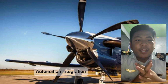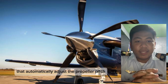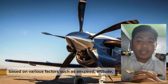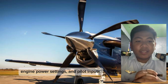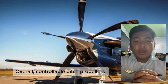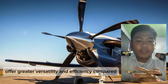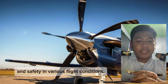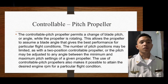Automation integration. Modern aircraft often feature electronic control systems that automatically adjust the propeller pitch based on various factors such as airspeed, altitude, engine power settings, and pilot inputs. Overall, controllable pitch propellers offer greater versatility and efficiency compared to fixed pitch propellers, allowing for improved performance and safety in various flight conditions.